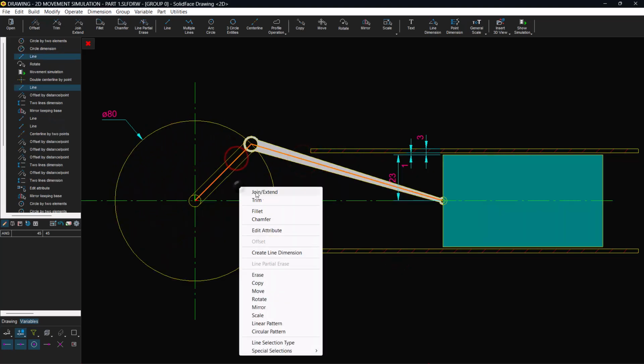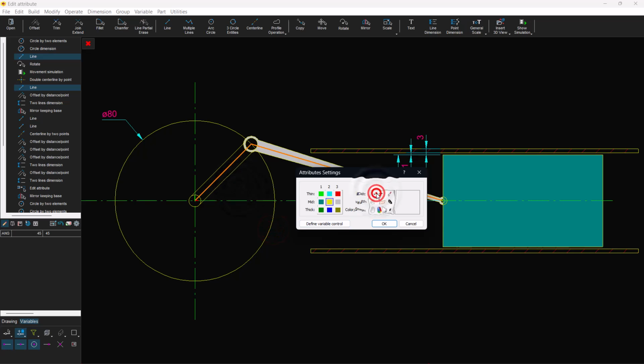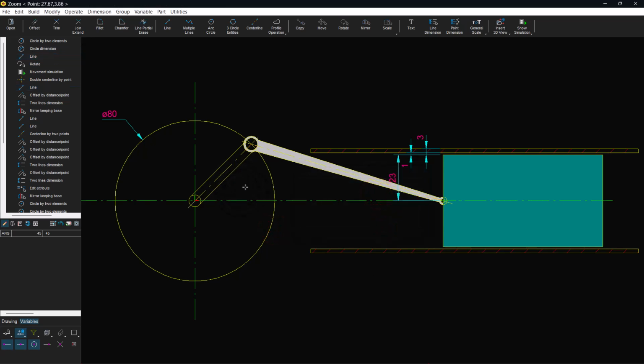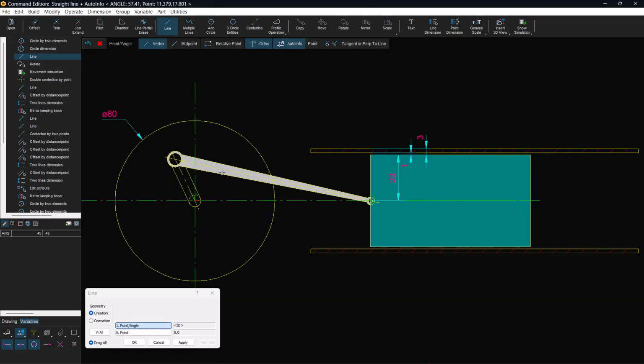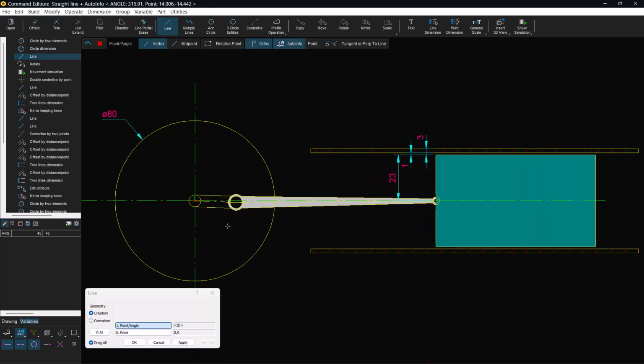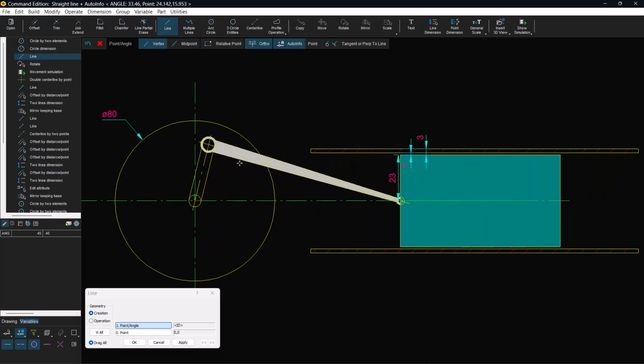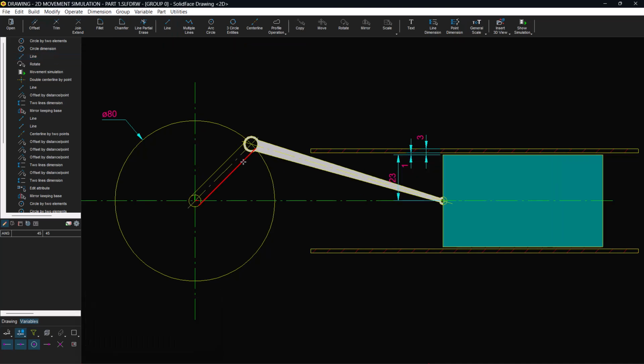It is important to test the simulation during each phase of the process. One simple way to simulate the simple movement is to click on the base element that controls the simulation and test it by dragging the line. If any errors occur, you can edit the geometry directly on the graphics screen and then build a new geometry. But in parametric or simulation constructions, if it is necessary to rebuild the geometry, avoid deleting them through their selection in the graphics area. That is, avoid the erasure and then construction of new geometries. Both actions will be stored in the command list and cause an overhead during each reprocessing cycle.